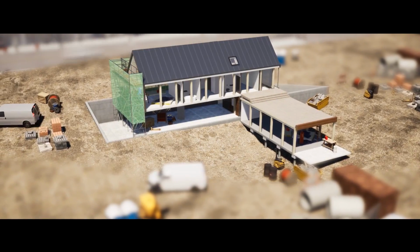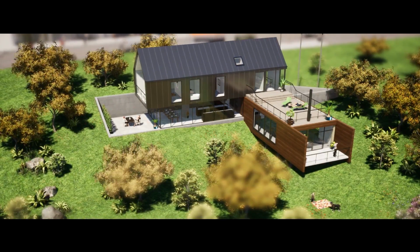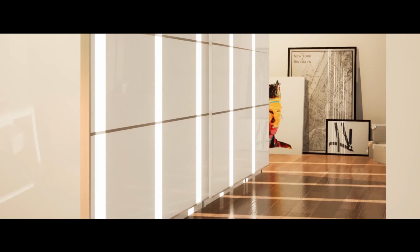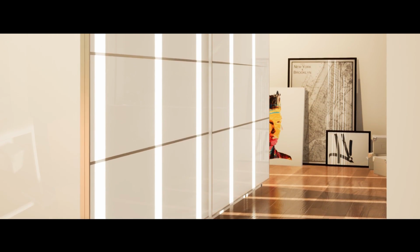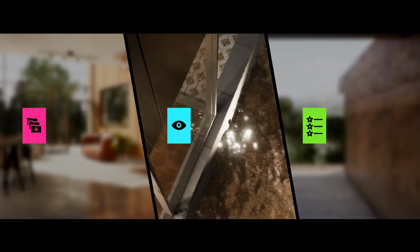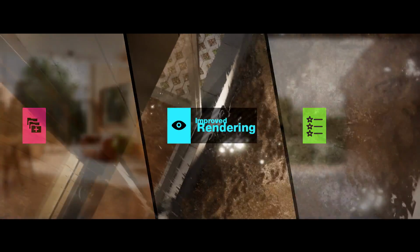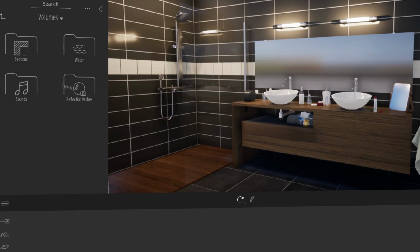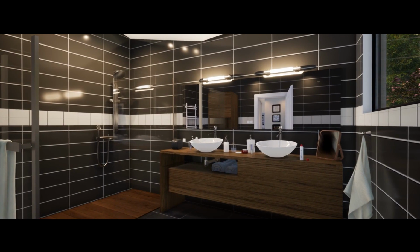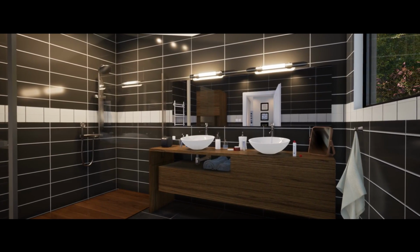Okay, next question. Can I do AR instead of VR in Twinmotion? No, Twinmotion is only VR compatible right now. When I apply mirror material inside the building, will I be able to see the outer environment? I'm not sure what you meant about the outer environment, but when you apply a mirror material, what you need to add in front of the mirror is a reflection probe, so you will see what is behind the camera. So when you are using the mirror material, don't forget to place a reflection probe.